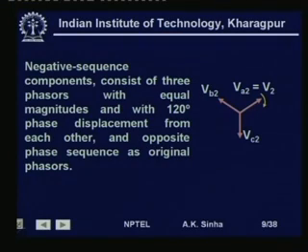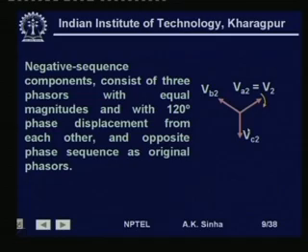That is, if we see this, the rotation of this phasor will appear to be in the reverse direction. So, phase A is here, then phase B will come here, that is, rotation will be like this. Or if we take the sequence direction in the same way, that is, rotation always anti-clockwise, then the phase sequence for this can be seen as A, then C, and then B. So, we call it the A, C, B, A phase sequence.